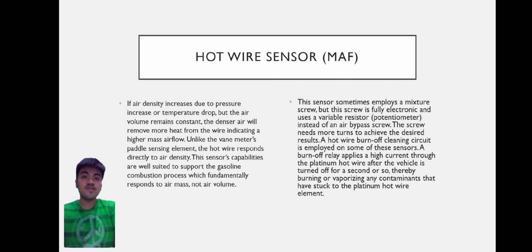These sensors tend to cause intermittent problems due to internal electrical failures. The use of an oscilloscope is strongly recommended to check the output frequency of these sensors. Frequency distortion is also common when the sensor starts to fail. Many technicians in the field use a tap test with very inconclusive results. Not all HFM systems output frequency. In some cases, the sensor works by outputting a regular varying voltage signal.